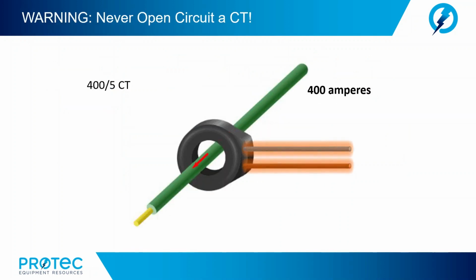Now, warning, never open circuit a CT. If the CT becomes open-circuited, it will try to develop enough potential to push the required secondary current, in this example 5 amps. With an open circuit, it can build up a very large potential and can cause serious injury.